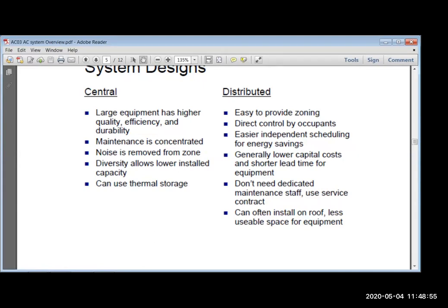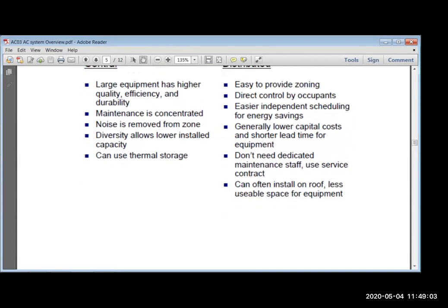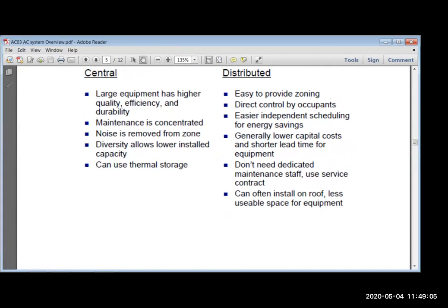So in millions of rupees. But a split AC system is very cheap and easily available. You don't need to import, locally you don't need a contractor, you don't need a supplier, you don't need shipment from a foreign country. So lead time is very small. Anytime you can go and install it within 1 day. But their life is not more than 7 years, commercial economic life not more than 7 years. On the other hand, the central system is very expensive, but it works for 30 years.